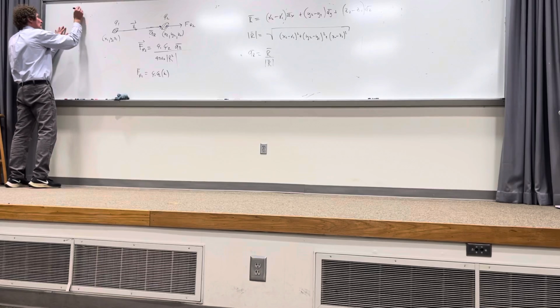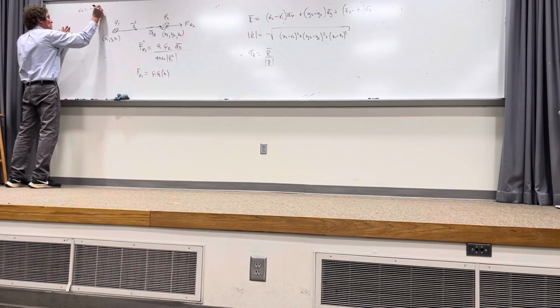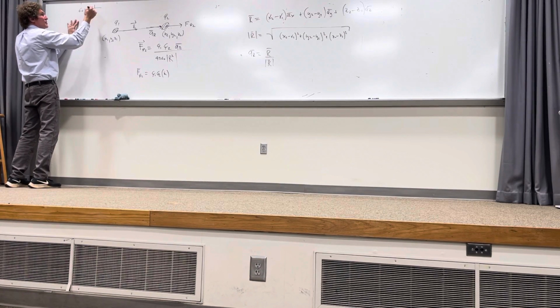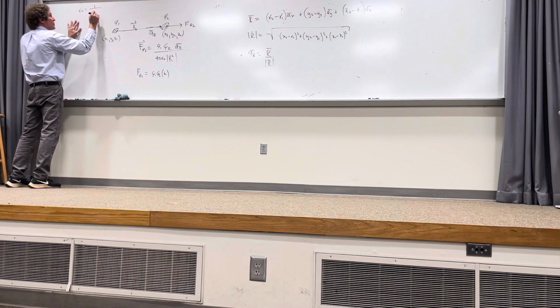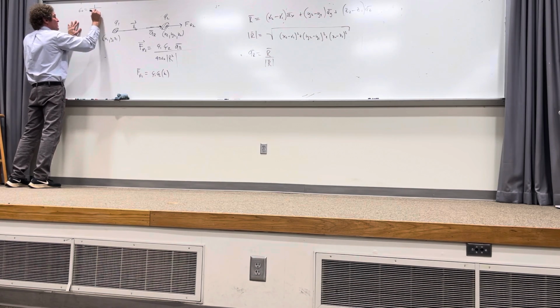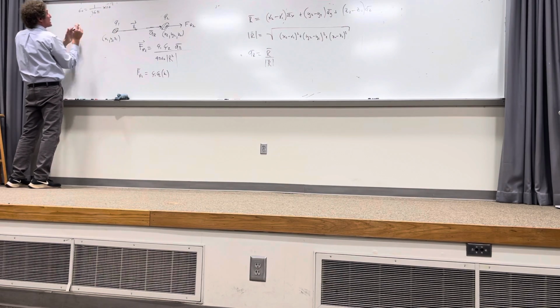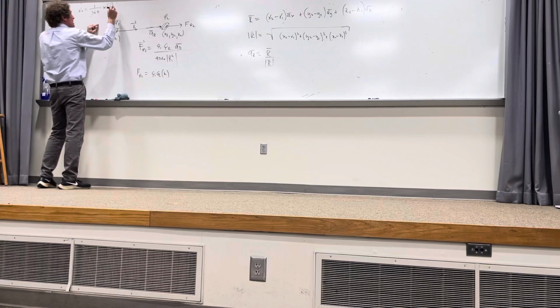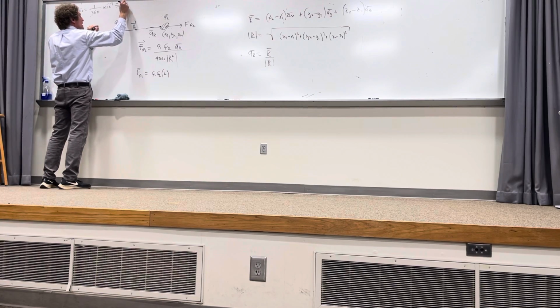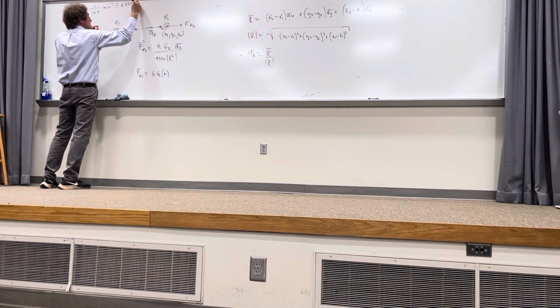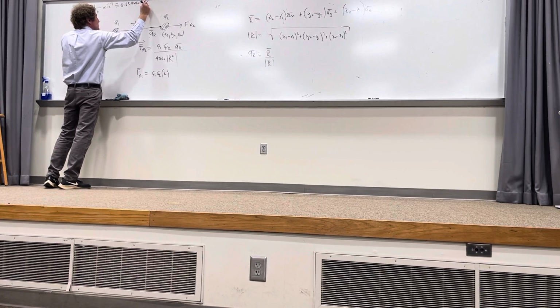And here, let me go ahead. Epsilon naught is really, the way he does it in his book, 1 over, I think, 36 pi times 10 to the minus 9th. Really, epsilon naught is about 8.854 times 10 to the minus 12 farads per meter.